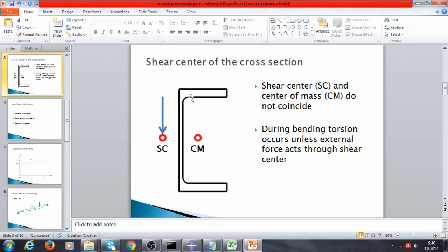That's something I found out while doing my research on channel sections. If you're using shell elements, you definitely need to modify your model to make up for torsional stiffness. You can modify it by using additional beam elements, which is more complicated. That's why I'll be using solid elements in my analysis.